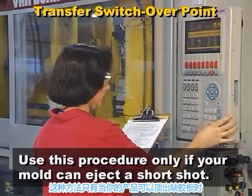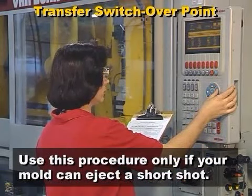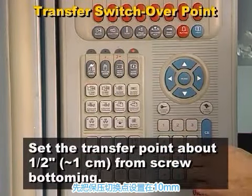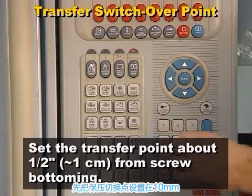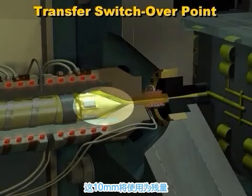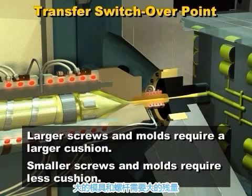This procedure should be used only if your mold can eject a short shot. You begin by setting the transfer point, typically a ½ inch, about a centimeter, from screw bottoming. Part of this distance will remain as the cushion, and part will be additional plastic packed into the mold. Larger screws and molds require a larger cushion. Smaller screws require less.